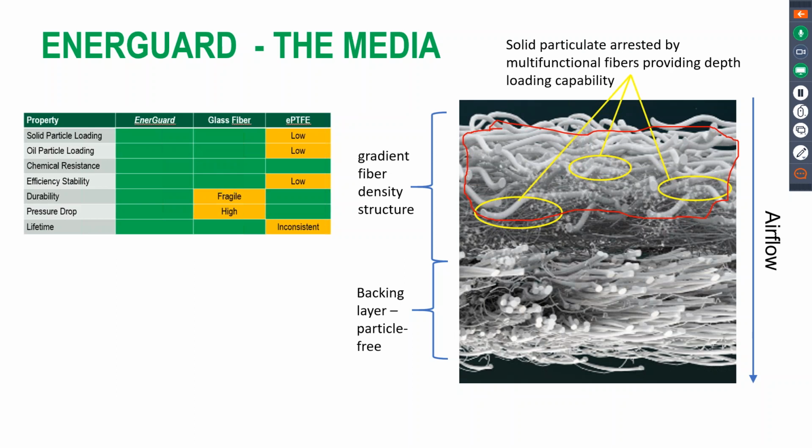Yeah, there are studies that have been done. They're primarily in the pharmaceutical space, but you can do the calculation as far as the reduced pressure drop and the amount of time that your product is in service, and you can do a comparison: okay, well, glass uses this much energy over this much time. If you were to have the EnerGuard media run at a lower pressure drop, then this much energy savings would be given back to you as a result of that differential. Okay. Interesting.